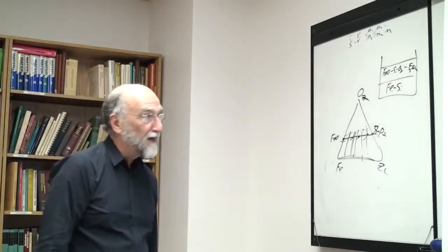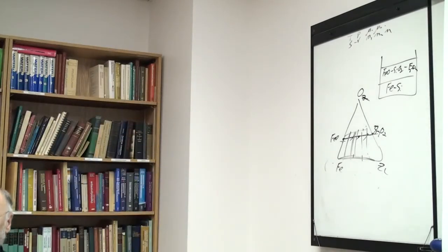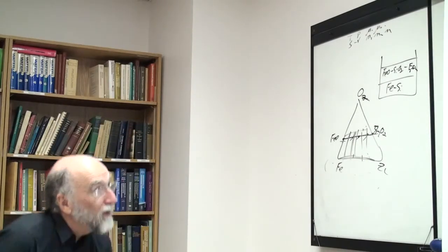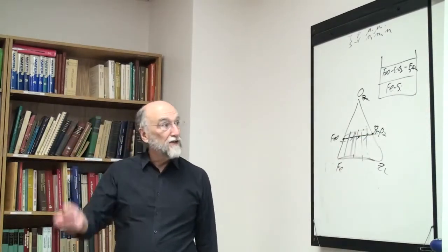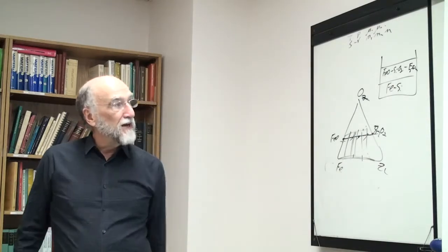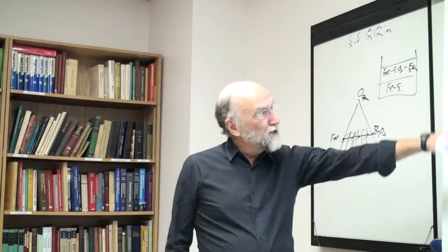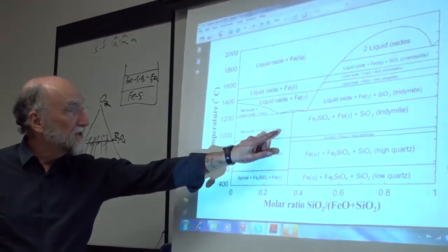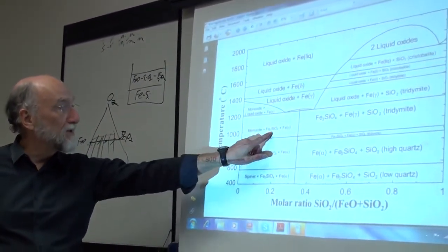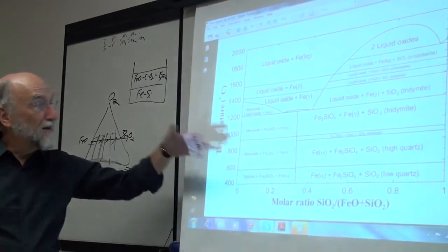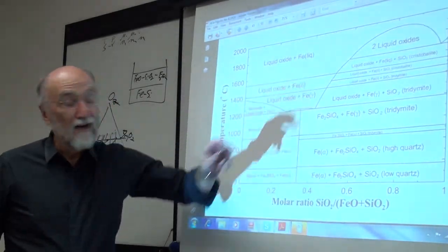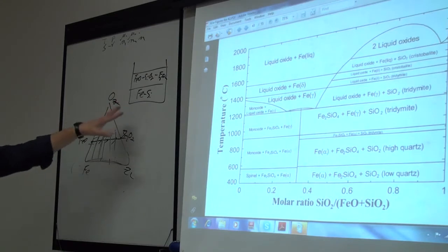So basically what I like to look at, so this diagram, anyway, the diagram still obeys the rules of binary phase diagram because you're on a line at which everything, two phases in equilibrium. Generally, when you see this diagram drawn in a textbook, first of all, you never see the iron. You see this phase would be monoxide plus Fe2SiO4. You don't see the iron written, but I put this in here to every phase field here. I've put in iron to indicate that really the iron is there. It's not an oxide diagram, it's a diagram with iron. The iron is present.